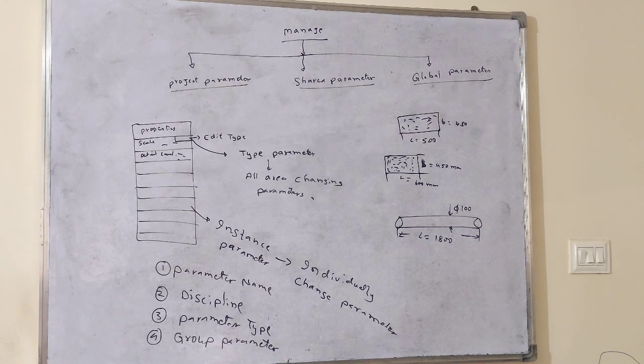Now if you select this other grid, in edit type we have kept 2, so it is 2. But in instance, it is not there. If you click the first grid, it is there, because we changed it for this grid. So instance updates individually, but edit type updates the entire type.